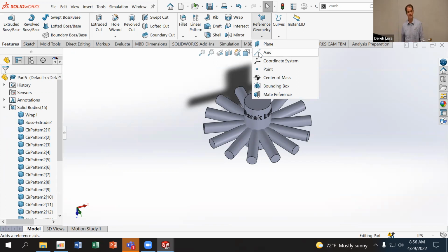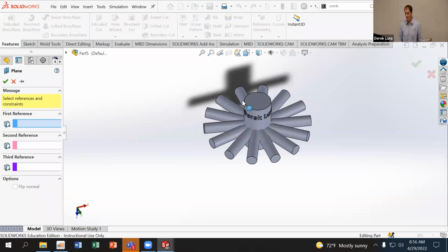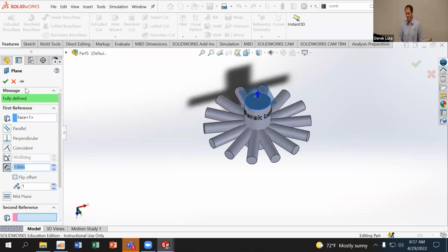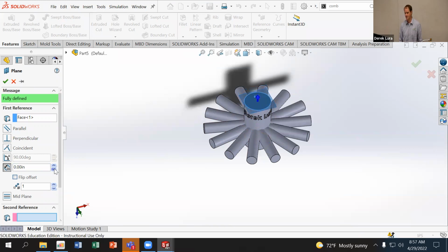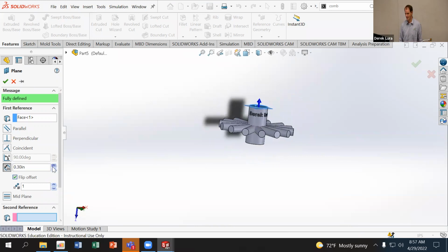Those are just whenever you want something to help you define the position of other objects inside the part. They're typically not used to make the parts themselves, although you can use things like offset planes to do cuts using the split tool, like we talked about before. And you can make fairly complicated parts doing stuff like that.